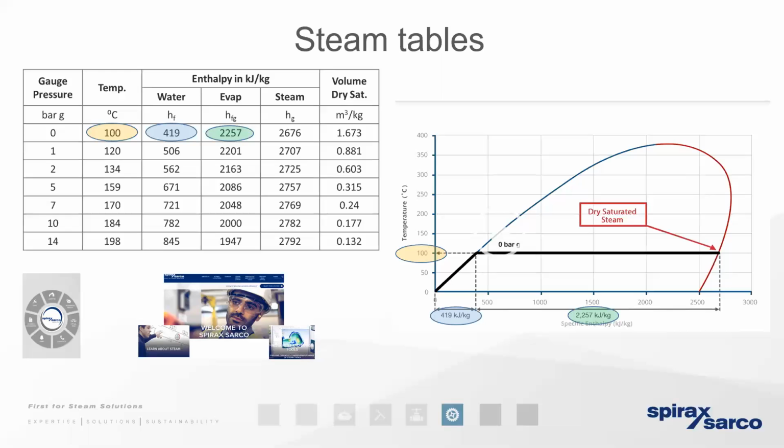It's simply got no value to us. In fact, we need to get it away from the heat exchanger, because if it starts to flood the heat exchange space, then we simply can't get enough of that energy rich steam into the heat exchanger. And of course, the process time will extend and extend.